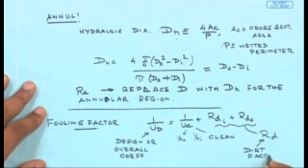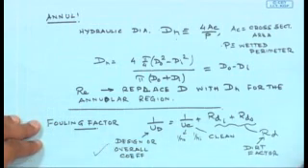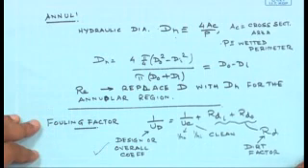So, this dirt factor and the clean coefficient together give us the overall coefficient which is to be used for all our design purposes.